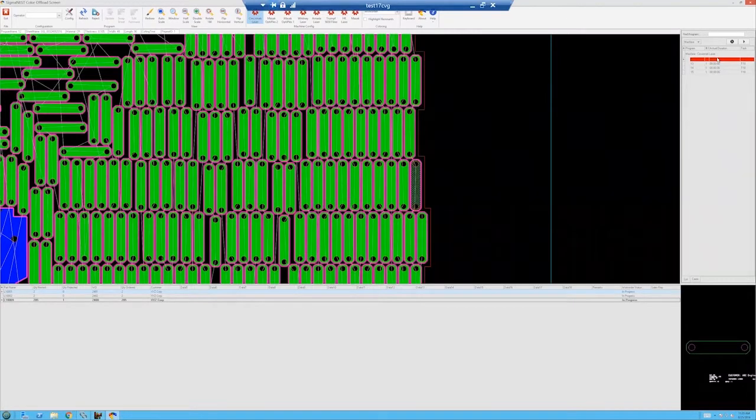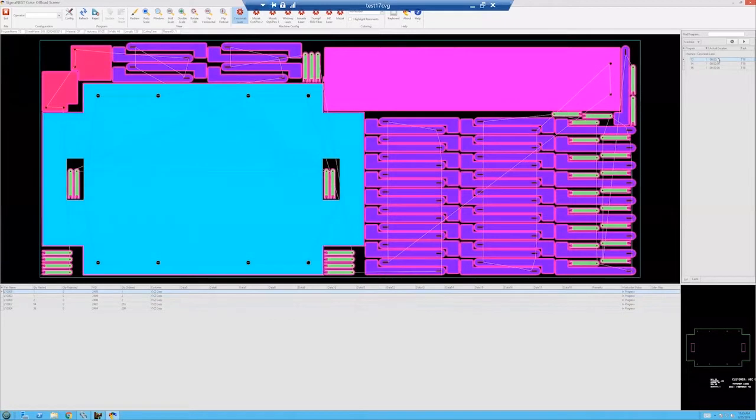And the nice thing about these tools on the shop floor is the second that I update it on the shop floor, it automatically updates the programming seat of SigmaNest to say this work order was complete, or like I mentioned before, 199 out of 200. Hey, here's this rejected part. We can actually create a classification for that rejected part to where when it shows back up on the work order list in SigmaNest, maybe it says emergency part or hot part. That way your programmer knows, hey, I've got this list of 10 hot parts that got rejected, maybe overnight on third shift when I wasn't here.